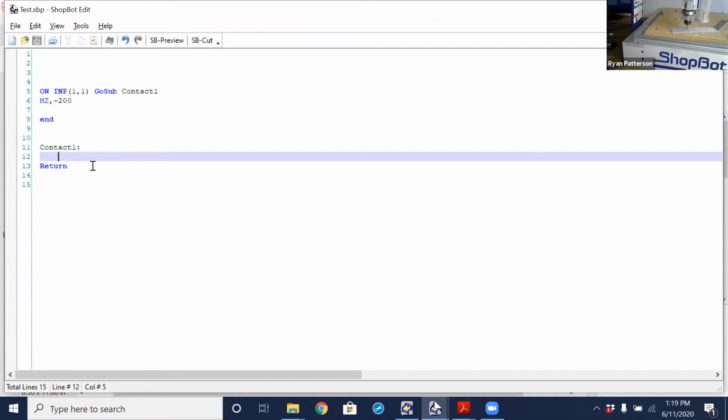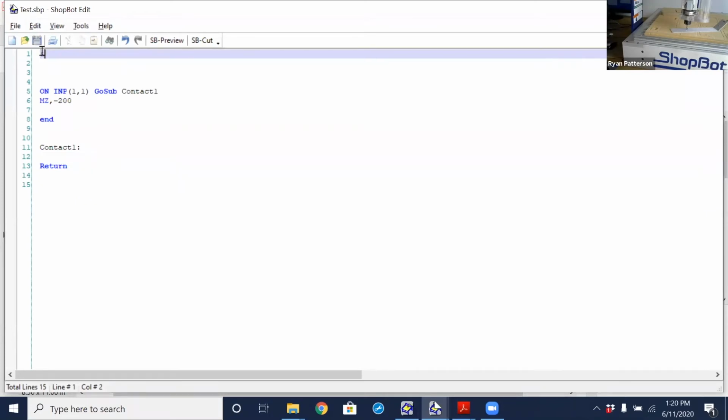And to be able to record that, I need another made-up word. This made-up word is classified as a variable. The variables all start with an ampersand. It's the little and symbol above the 7. And I am going to label that Z2. I'm going to tell it that it equals 0. That's not doing anything by itself other than saying that Z2 is going to have the value of 0.